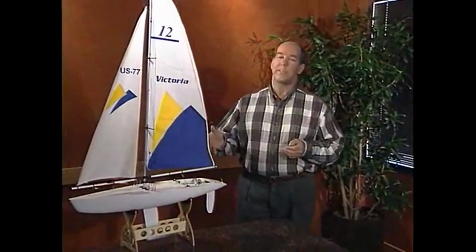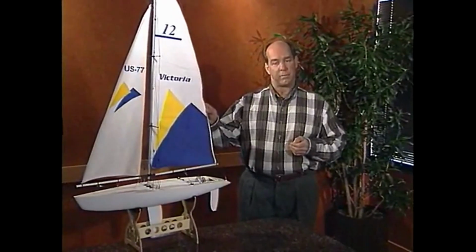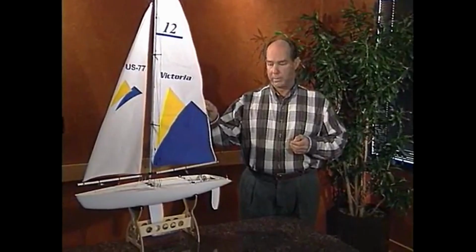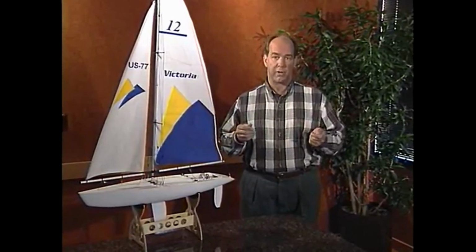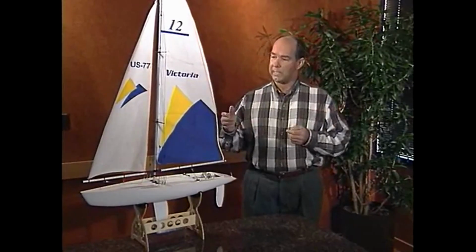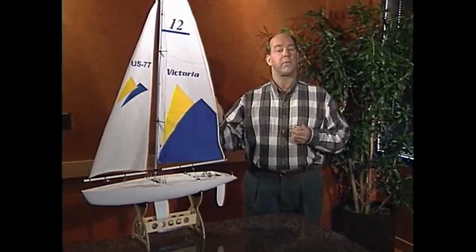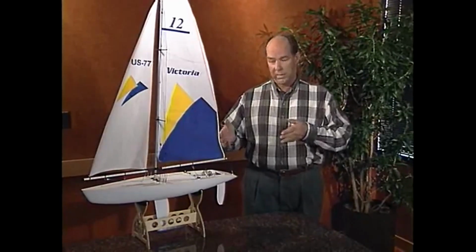Here's a more practical way of illustrating how you can get a big push from a low pressure pushing on a larger area. Consider a sailboat. This toy boat has a total sail area of about 300 square inches. Just a moderate breeze generates a pressure of about 1/10 of a pound per square inch. By using our engineer's formula, we can see that such a breeze would exert about 30 pounds of force on our toy boat. That would be more than enough to move it through the water.